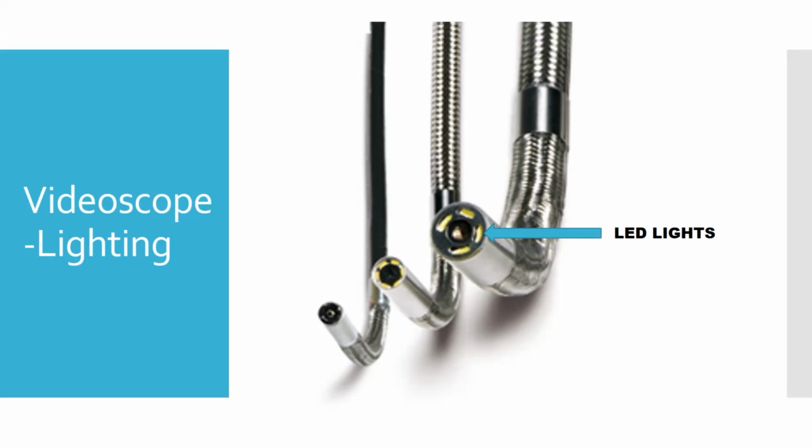Feed it through a tube. You get a piece of hydraulic tubing and you slide your scope through it and basically turn it into a rigid scope, like a borescope, and use that tube. In fact, for certain inspections, Pratt & Whitney and GE sell kits of pre-bent tubes.